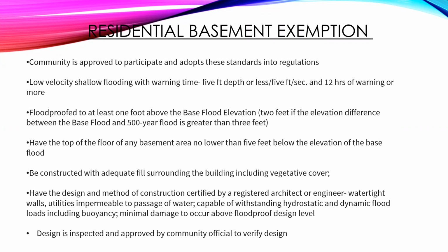It's not necessarily about the floodproofing system in the same way. It does have to comply with ASCE 24 still, and that is also written into this certificate that I'll show you. And then finally, it is inspected and approved by a community official or a representative for the community to verify that design. And so usually that means floodproofing the basement, extra rebar to reinforce around the top of the walls to withstand all of that pressure.